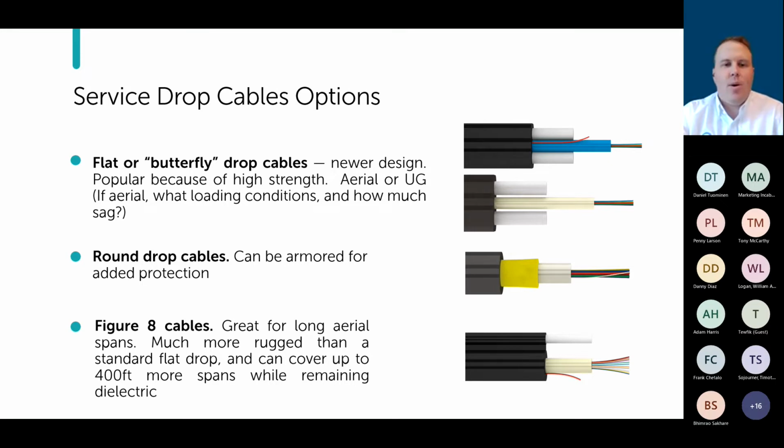You can go with a round drop cable and even go with a small armored cable as well. You've got some different options there. It's not as popular, and the main reason for your standard flat drop cable being the more popular route is just because of the cost. It's a lot more cost effective, a lot lower price. So the general consensus is, if somebody cuts it, the cable itself costs 10 cents a foot, 15 cents a foot. Go out, have somebody replace it, and call it a day.